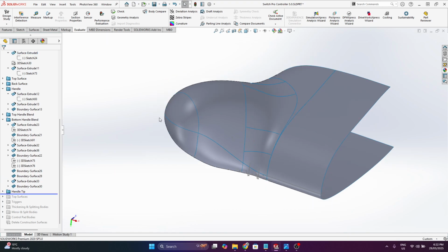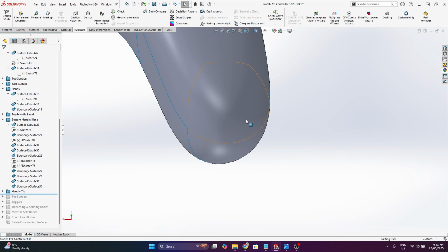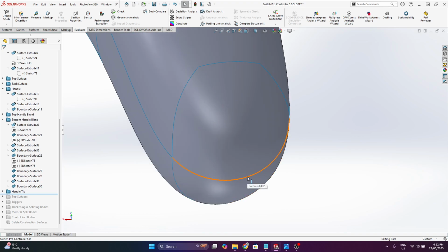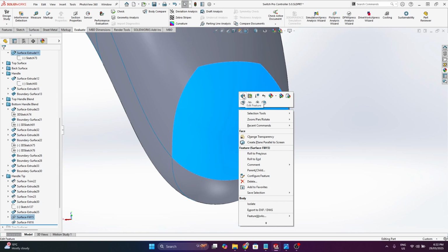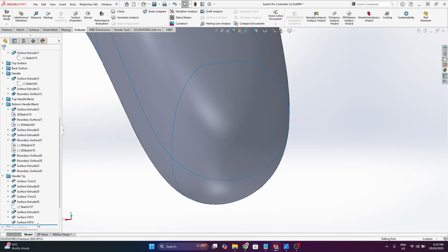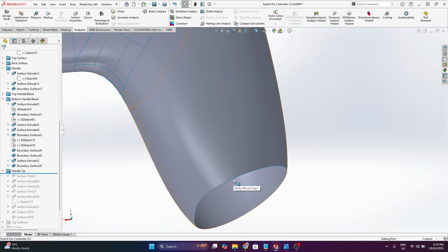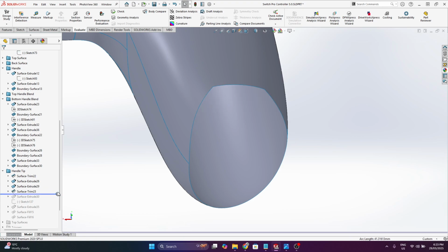Producing the handle tip. Just go into this. So I mentioned in the first model that I made that was incorrect, I'd done it in a way where I end up with a point where the surface is collapsing on itself. SolidWorks, or NURBS surfaces generally, like 4 sides. So what I'd done is trimmed away this section, because this just gives one edge or one side. Trimmed it back a little bit first, and then trimmed away to give multiple edges.